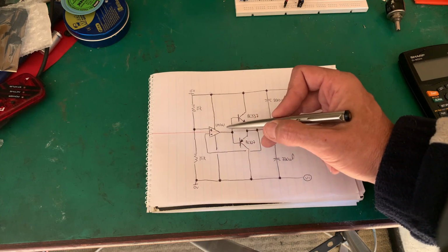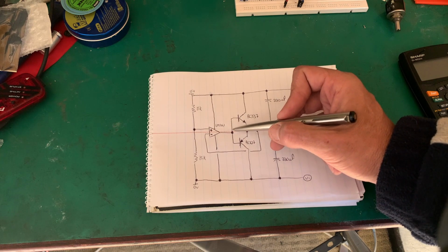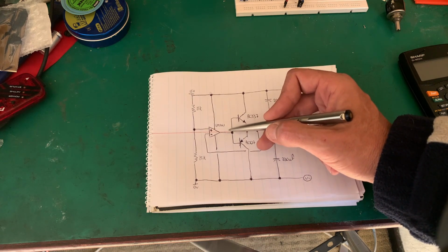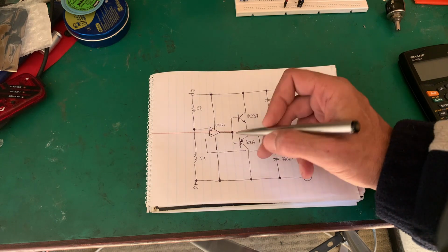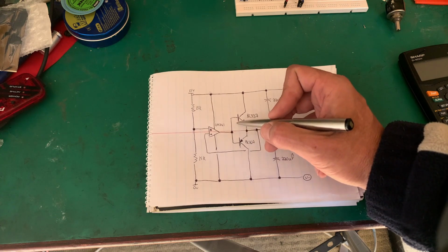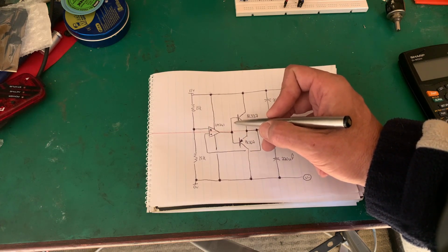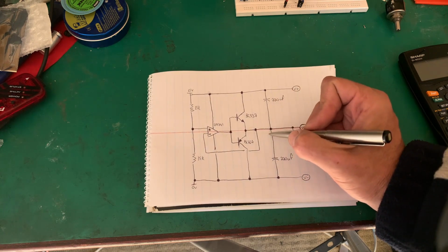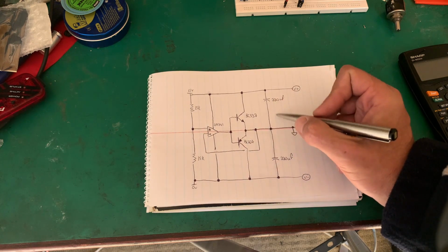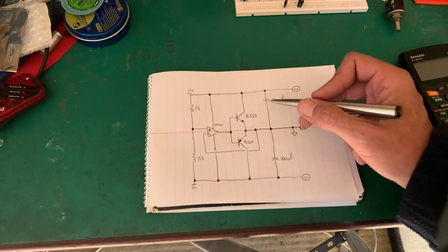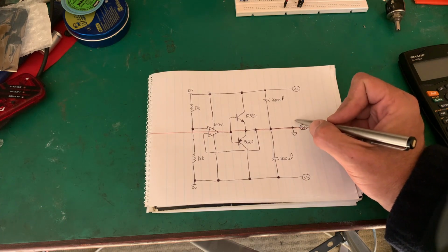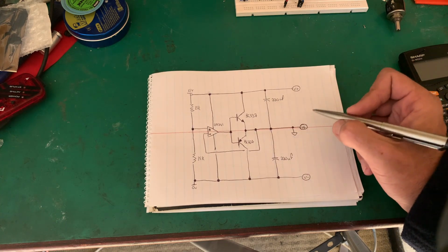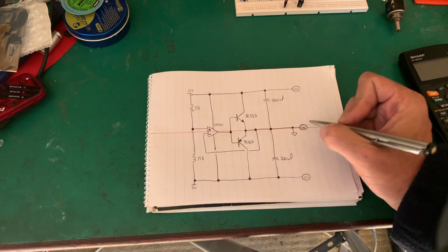Those two start meeting. This output either stays the same where it was if it's controlling, or it starts cutting back if that's going up too much. So it goes down a bit more, switches that transistor off a little bit and that one on a little bit to pull that down to ground. So we're keeping our 7.5 volts. Those two capacitors are helping to smooth it. So this becomes our new 0 volt or virtual ground.